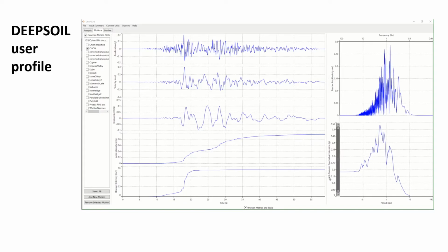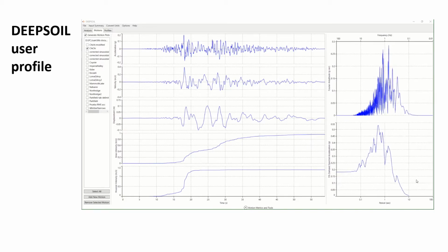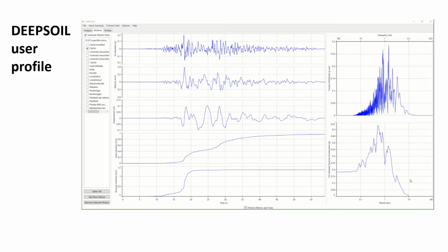In this case, with a 5% damped spectral acceleration, I believe that you can change the amount of damping ratio of that spectral acceleration. But this will be a very useful tool, as you have probably seen for the case of a Seismo Signal, and this graph here at the bottom right will represent the period, or the different zones within the periods of a single degree of freedom system subjected to these time histories or this seismic motion, where it will be more damaging or more dangerous.